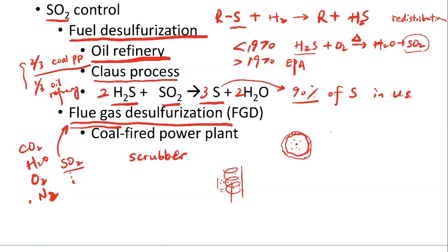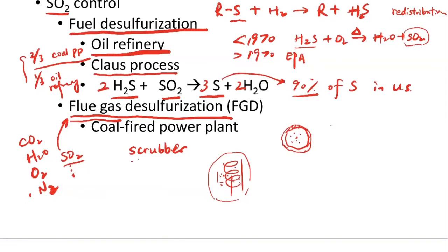If it's larger, then they're going to have a higher inertia and then get easily captured. So the scrubber for the sulfur dioxide is going to be a little bit different in terms of the detailed design, but it's also using water droplets to deal with the problem, okay? And by the way, scrub just means wash, right? It means cleaning. So the scrubber means that we want to clean the sulfur dioxide out of the flue gas, okay?